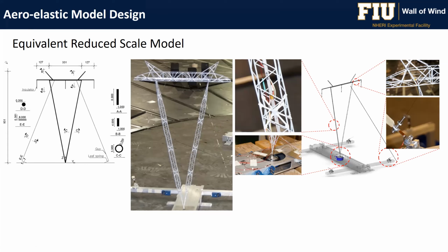And I must say here, for this particular model, we simulated the dynamic properties using the frame structure that you see on the left. However, this doesn't mimic the shape of the structure, so we needed to add non-structural elements, the cladding elements that you see on the zoomed-in photos on the right. Together, the two mimic both the dynamic properties, frequencies and mode shapes of the structure, and also the shape, so we can replicate the wind forces on the structure.